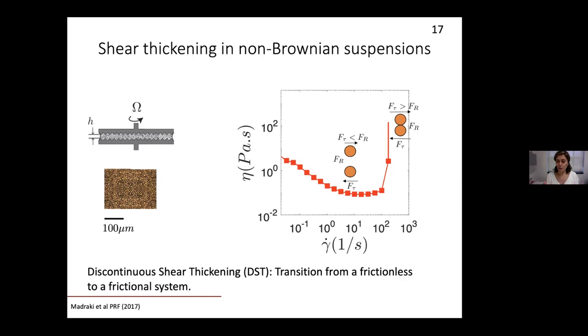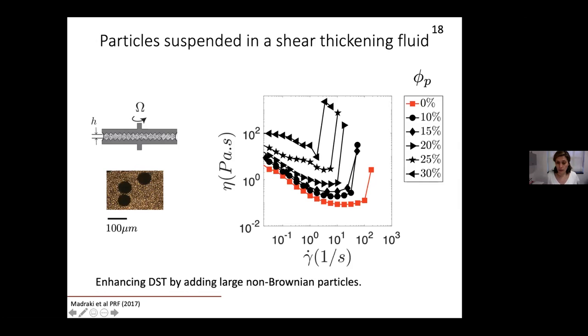And then at that point, friction becomes activated, and you know that friction is a highly dissipating force, and that's the reason that you get a huge jump in the viscosity in such materials. So basically, the balance of repulsive force and shear stress would give you a critical shear rate or critical time scale in the problem, if you wish.